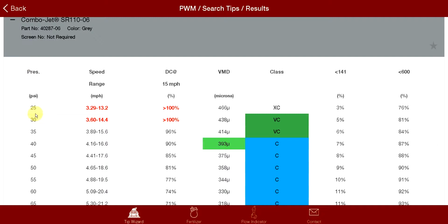So even though you'll see the pressure being 30 psi in the cap for the larger tip series, if there's a significant pressure drop, the actual pressure at the tip will vary. It'll be lower than that, at the very least. The bigger the tip, the more that pressure drop influences the spray, so keep that in mind when we're considering what our lowest pressure should be.